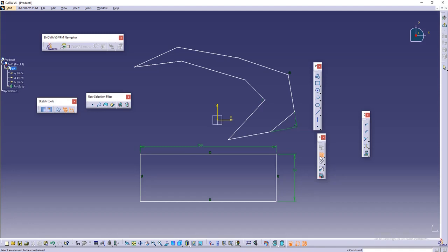So it has to be symmetrical or in the center that you can create, or you just have to constrain it, right? So if the horizontal line is here, I can use this line and this line, right? Now it is showing one line like 86.1. Once I click here, what happened? These two lines are showing in green, which means this is the right thing we have done, and this shows that you have created the exact constraint from the center.